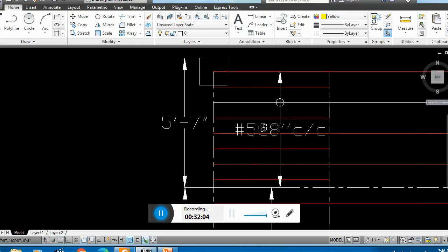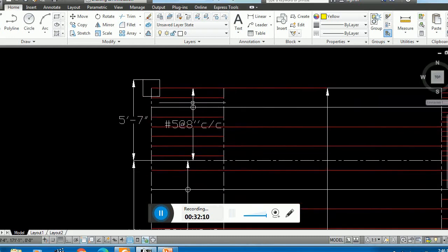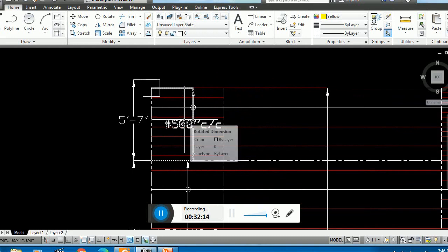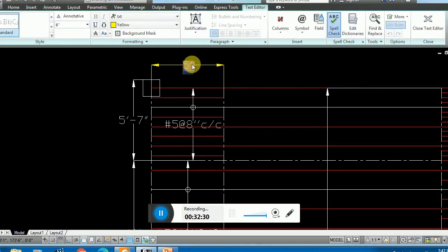Although the negative moment is minus 14, the capacity of this reinforcement is 18. Now remember, this is placed in the column strip width. Let me show you. This is the column strip, and you know about the length of this column strip.